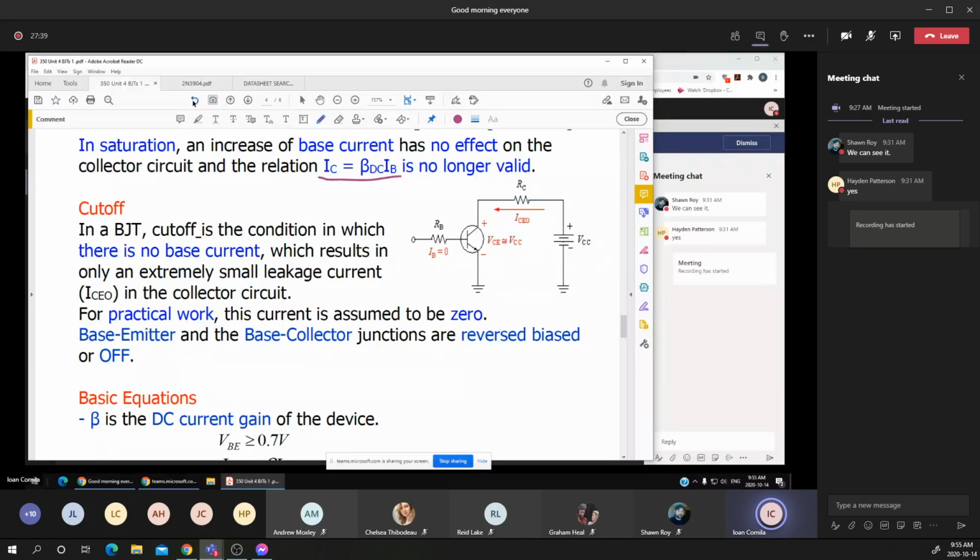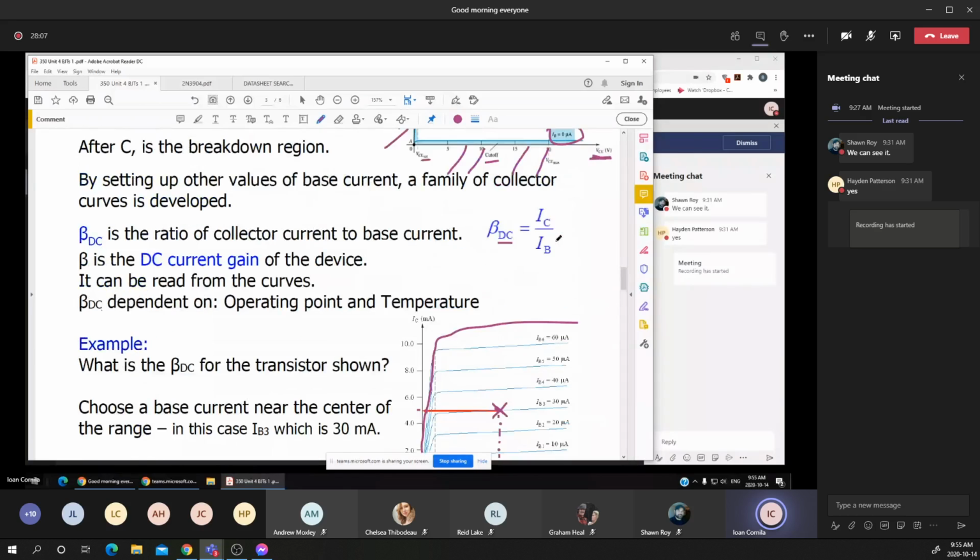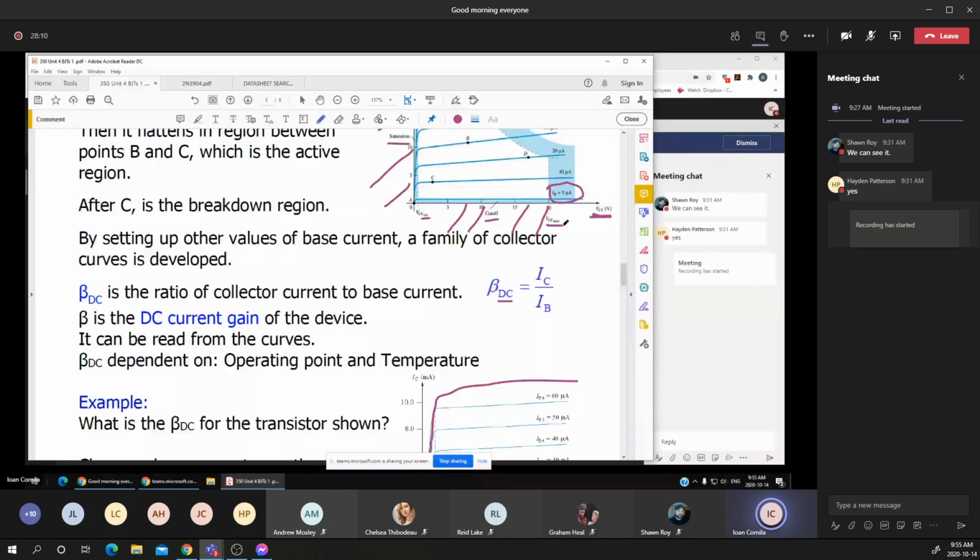Remember that we discussed the open circuit and the closed circuit. The transistor will act as an open switch, or is in an off state, the cutoff region or the off state of the transistor. That's the VCC, which is equal to the VCE in the cutoff. Going back to the diagram, you notice that I'm having the VC max. The VC max is actually equal to the supplied voltage VCC.